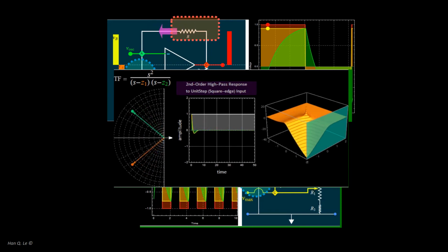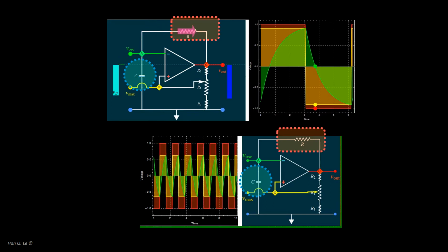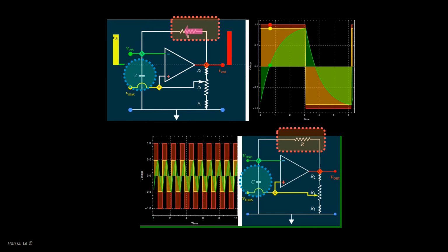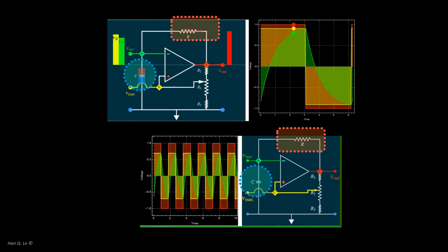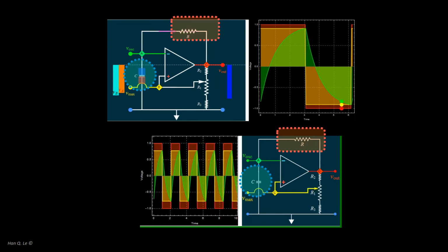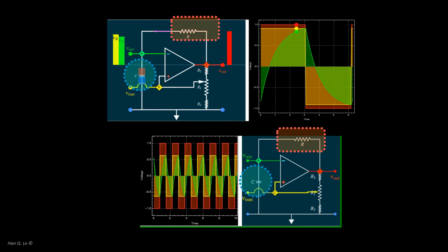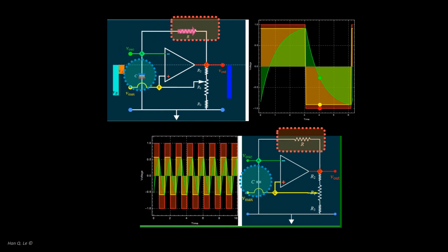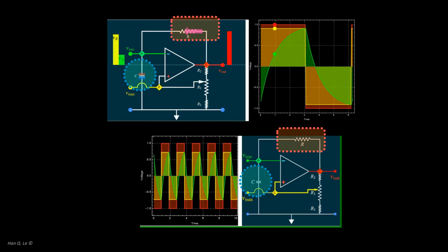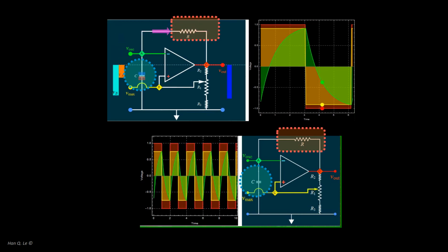Don't worry if you have not learned Laplace transformed circuit yet. It is sufficient here to realize that RC time is not just about the current exponential behavior in the charging and discharging as seen in previous A1 demonstrations, but is also related to the oscillation frequency of a circuit. Hence, this OpAmp self-oscillatory circuit is intended to further reinforce your intuitive understanding, or quote-unquote gut feeling, about the connection between the RC response time to frequency. It is also a prelude to the concept of using RC time in frequency filters later and in Lab 6.